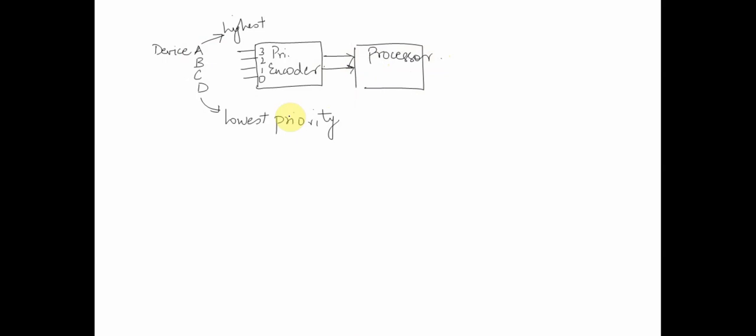So this is all about this particular lecture. We talked about two combinational circuits, decoders and encoders. For decoders, we saw min-term generators and max-term generators. We looked at the 2 to 4 decoder and 3 to 8 decoder, and then we looked at how min-terms and max-terms are generated. We created a 3 to 8 decoder using 2 to 4 decoders. And similarly, we then looked at encoders and various variations of encoders and decoders with different valid signals, and priority encoders also.